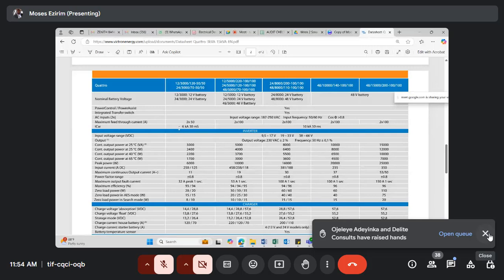So that's the reason why, if you understand that principle, you will definitely know that, okay, this particular customer that operates at night, maybe it is residential, then you can now install a hybrid inverter. That's the reason why you see people installing hybrid inverters for residential, not battery inverters. Do you get that? Okay. So that means for a hybrid inverter, it is not only charging the battery but also powering the load.